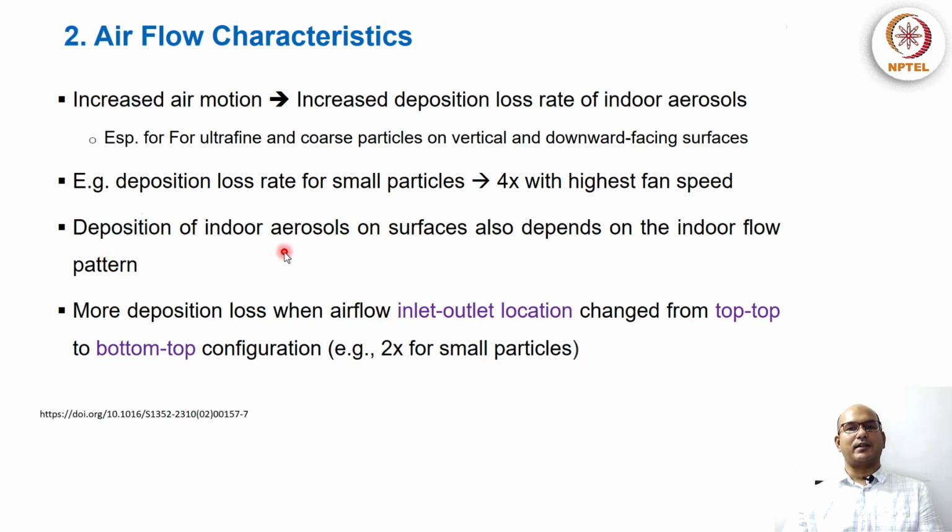Then also the pattern is important. Deposition of indoor aerosols on surfaces also depends on the indoor flow pattern. More deposition loss was observed when the inlet-outlet location changed from top-top to bottom-top, almost 2 times for small particles.